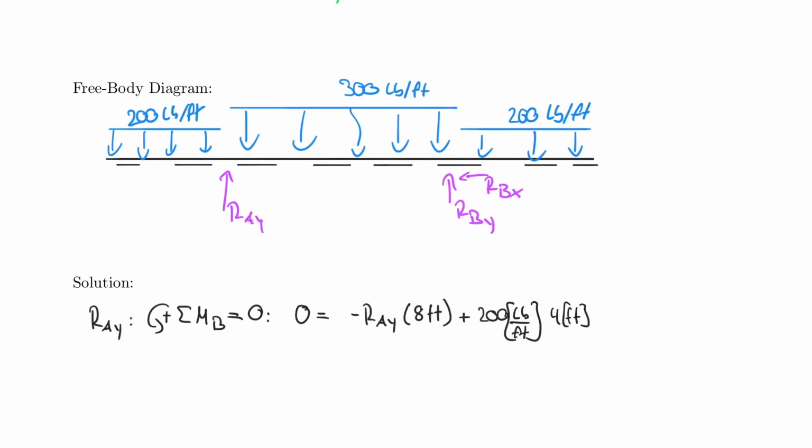And now I need a lever arm, and the lever arm, of course, is from its center to here. So this is 4 plus 4 plus 4 halves. So really what I'm looking for here is 4 over 2 plus 8, let's say, feet. And that is the lever arm of the first force. And now I have the 300 that also rotates counterclockwise about this point because it's lumped here in the middle.